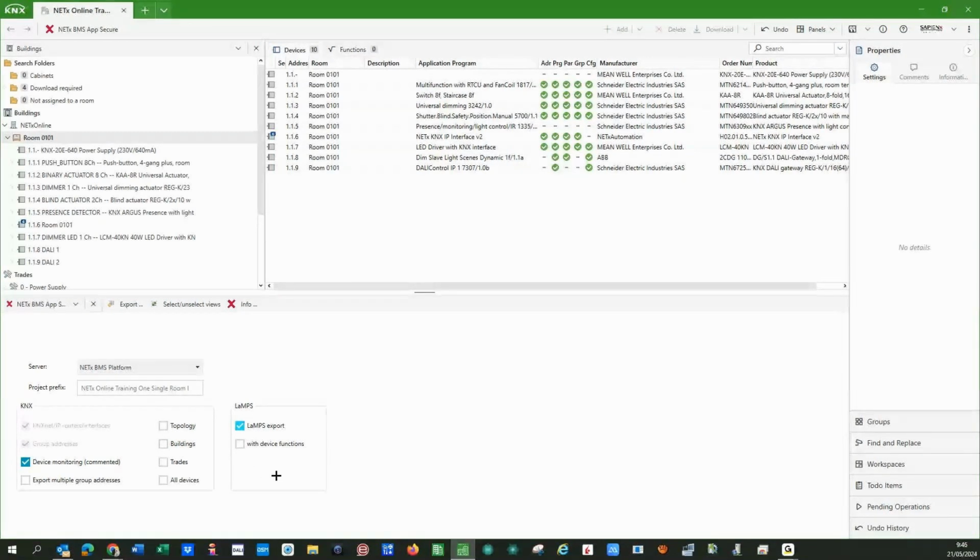Lighting management in terms of DALI, for example, in terms of any lighting circuit management. So it's important, if you have DALI, as we are trying to simulate that we have DALI in our installations, to export lamps. It's not a problem to include it now. So this is the basic configuration, the default configuration, that I will respect in this case. Okay. So just select the export button.